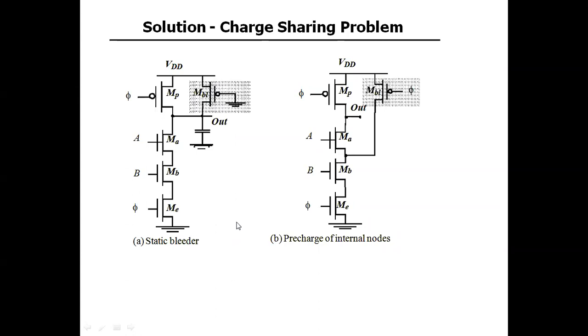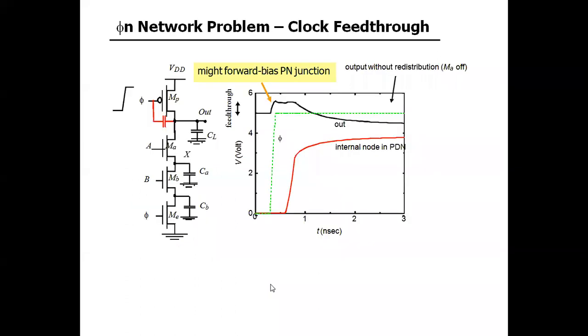Or you can go for pre-charge of the internal nodes, the internal loads. So by using these two ways, you can address this charge sharing problem, right?